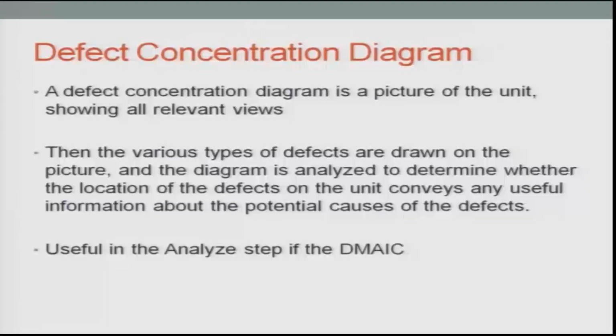Defect concentration diagrams are there. A defect concentration diagram is a picture of the unit showing all relevant views. Then the various types of defects are drawn on the picture, and the diagram is analyzed to determine whether the location of the defects on the unit conveys any useful information about the potential causes of failure, or causes of not-so-efficient performance of the system.